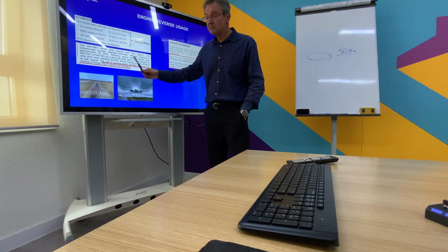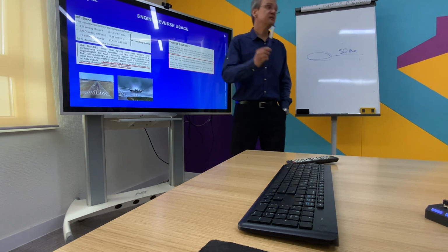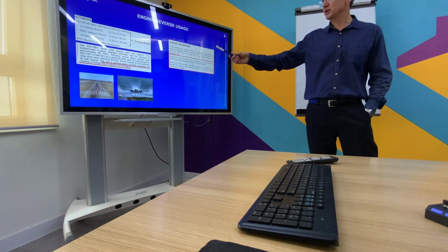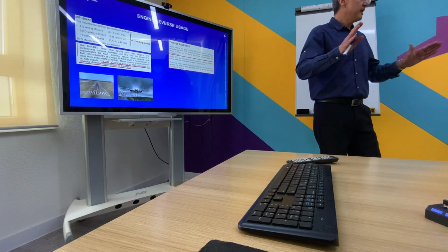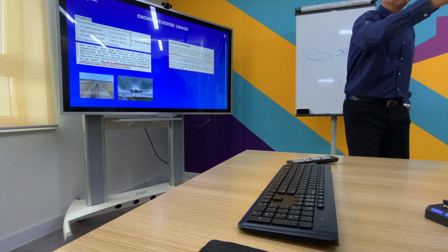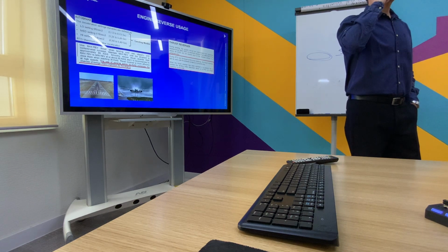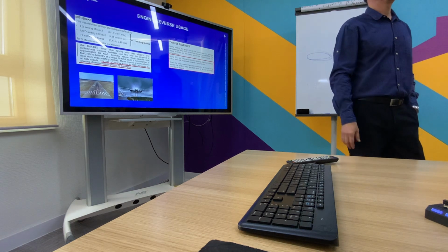But there is a statement on the AOM that using reverse below 60 knots, you may increase the foreign object ingestion. What I recommend to you guys, if you don't need to use reverse to stop the airplane for safety concern, when I hear the call out 60 knots from the monitoring, stow the reverse.